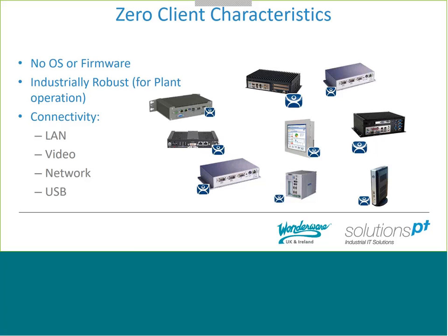What some people like to have is that because they don't want to do fault finding between failure of the client or the display, if you use them both stuck together, both the same unit, it doesn't matter if somebody's put a screwdriver through the screen or there's been a processor failure on the board of the thin client, the operator just changes one out and replaces it with another. So the thin clients within Thin Manager are very, very easy to replace. Probably 2-3 minutes, something like that, to get them swapped over. So very easy to manage and very, very secure.